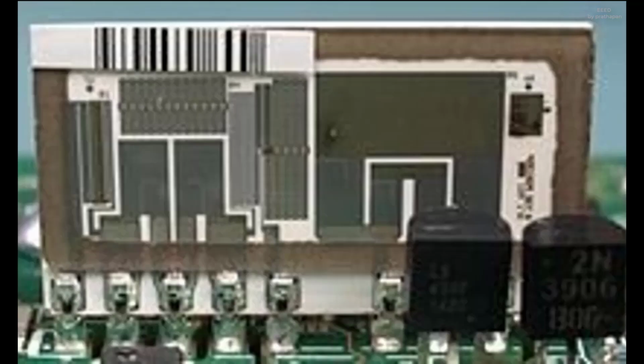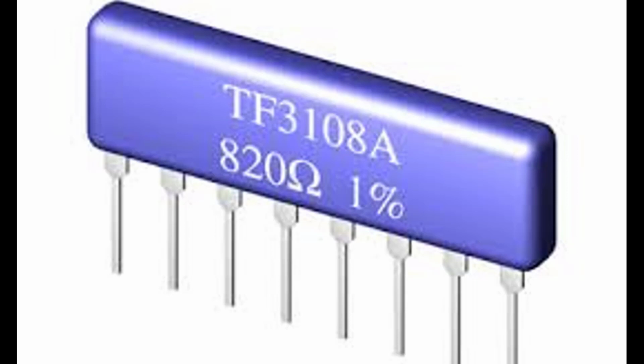Thick film. Laser-trimmed precision thin film resistor network from Fluke, used in the Keithley DMM7510 multimeter. Ceramic backed with glass hermetic seal cover. Thick film resistors became popular during the 1970s, and most SMD, surface mount device, resistors today are of this type. The resistive element of thick films is 1000 times thicker than thin films, but the principal difference is how the film is applied to the cylinder, axial resistors, or the surface, SMD resistors.